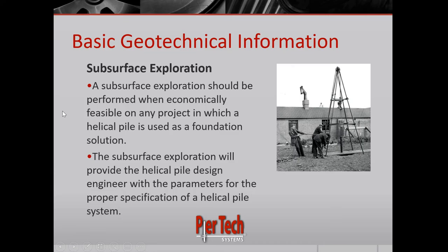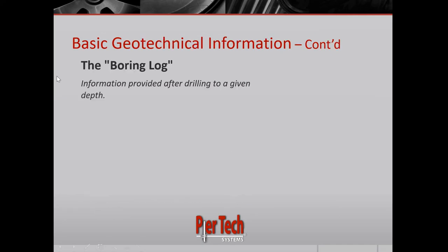During this subsurface exploration, the driller will be taking down information, and also the geotech engineer will be doing lab tests that will provide the helical design engineer with certain parameters to be able to specify the proper helix size, shaft size, and depth for the project. The key component to this report is the boring log. There's a lot of great information contained within it after the drilling is done.